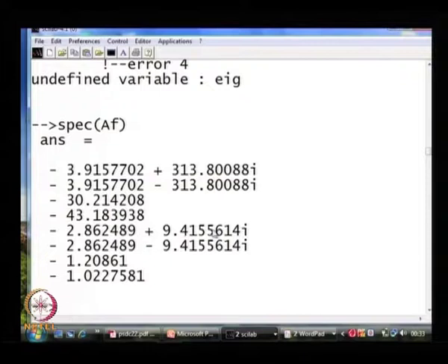You will find that these two new eigenvalues are coming because of the inclusion of the electromechanical equations. The mechanical equations contribute the equations corresponding to omega and delta. So, basically you get these two extra eigenvalues compared to the eigenvalue analysis of a short circuited synchronous machine.